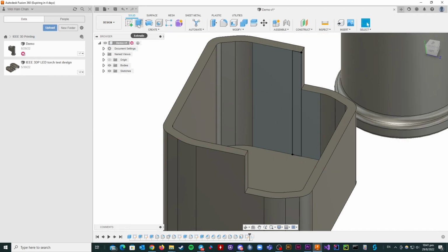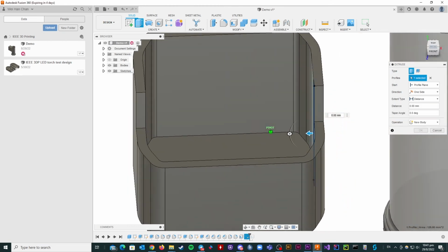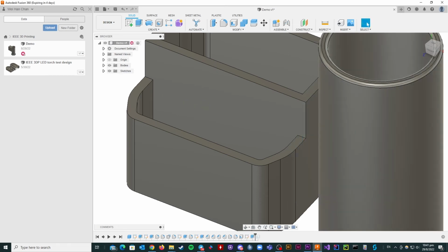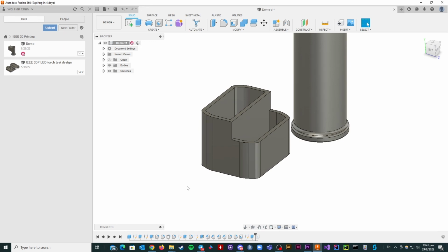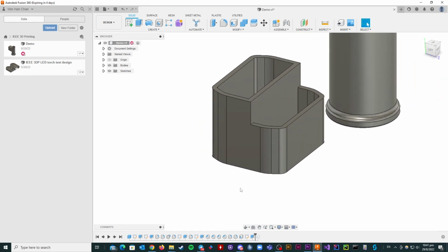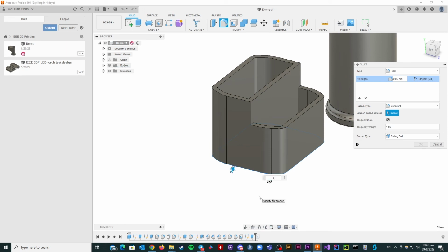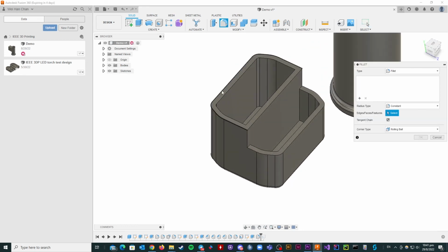So finish sketch. Extrude, select this sketch that you've just done. Sometimes, instead of pulling, you can in fact just select that next surface and it will match the length accordingly. So there you have a divided pen holder. Of course, a few more improvements that we can do. We can give this a bit of an additional fillet down there. Let's say 3 millimeters. Now let's continue to edit it a little bit more.